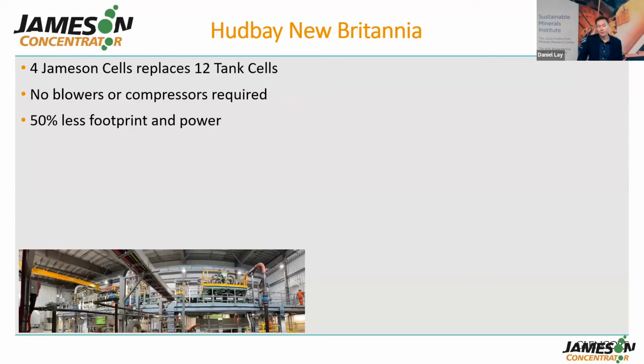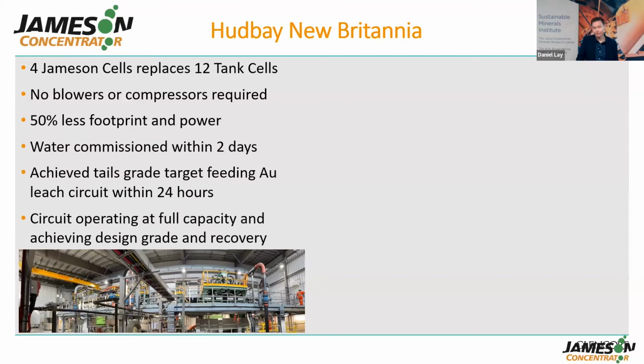So we had 4 Jameson cells, which replaced a circuit of 12 tank cells. No blowers or compressors were required. And this resulted in a 50% decrease in footprint and in power. It was water commissioned within 2 days and achieved the target tails grade within 24 hours of starting. The circuit's been operating at full capacity and achieving design grade and recovery.